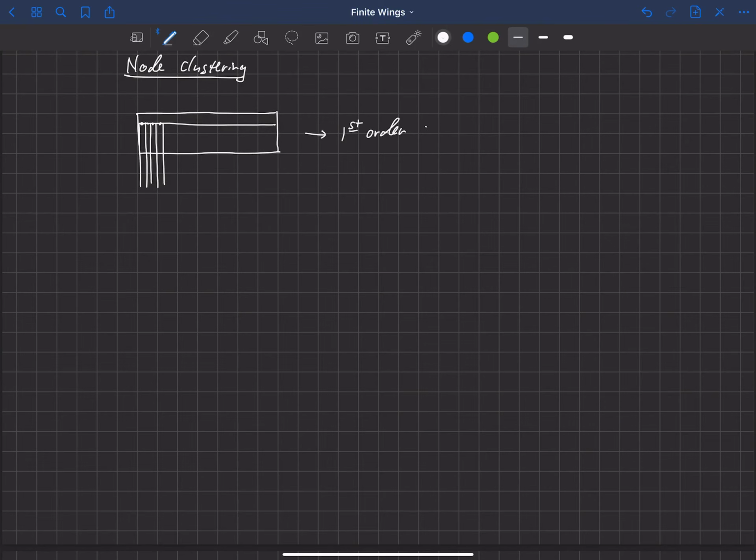and the order of convergence tells you how quickly you will approach the correct solution. If I keep doubling the grid, so if I start off with n equals 20 and then 40 and then 80, as I double it, do I cut my error in half? If so, every time I double it, if my error gets cut in half, then that's called first order convergence. And so we can continue to converge until the error in our solution is acceptably low.